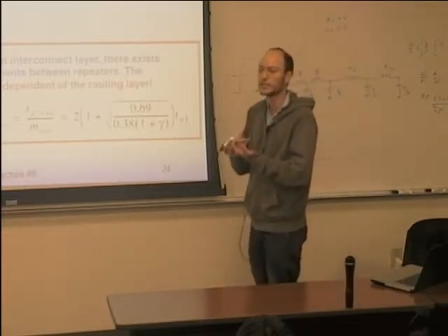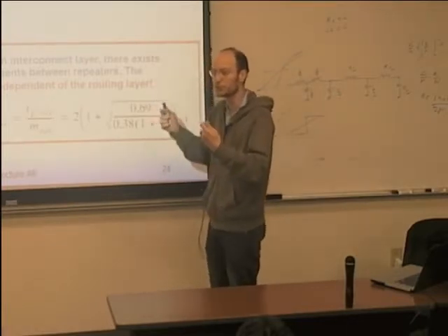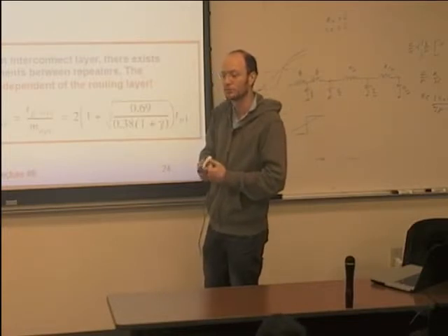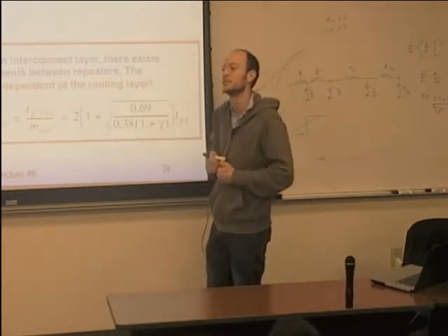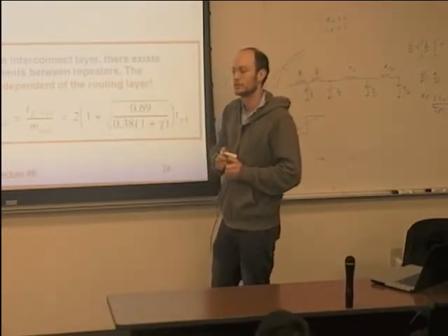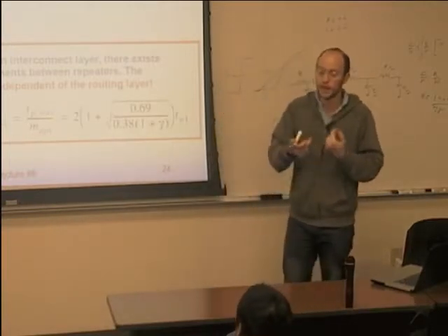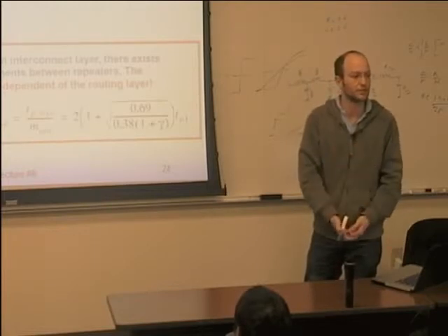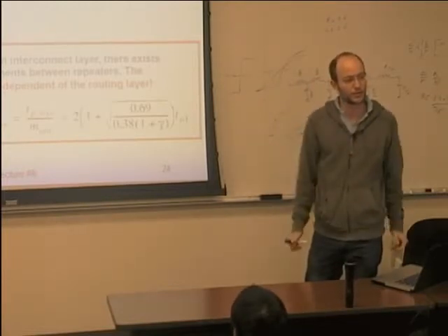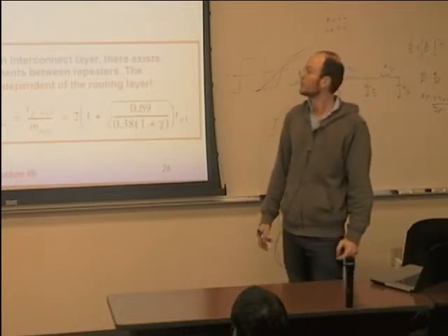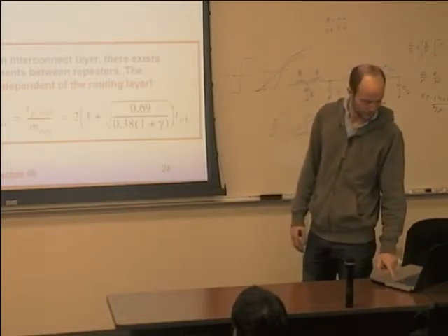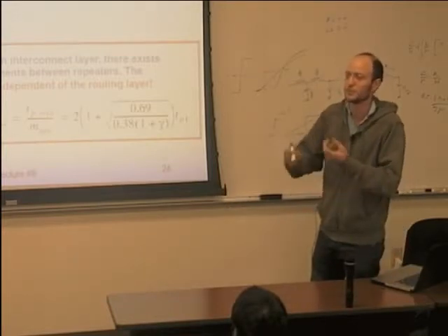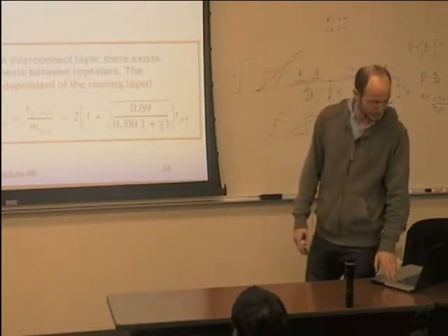But the bottom line is that the delay of these wires, okay, after you do this optimization will be independent of what wire you started with, okay? Because what you are changing is you are changing the length, okay? To make it similar to the delay of an inverter. This is really the big picture, okay? So, I mean, this is pretty remarkable. It's just math. You do the math, this comes out.